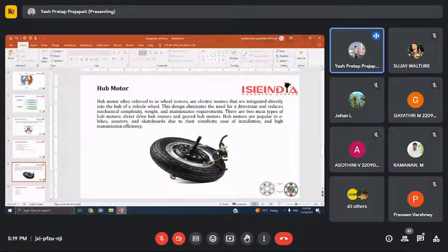Ordinary electric motors use a mechanical device called a commutator and two contacts called carbon brushes to reverse the electric current periodically and ensure the axle keeps turning in the same direction. Hub motors are typically brushless motors, sometimes called brushless direct current motors or BLDC, which replace the commutator and brushes with half a dozen or more separate coils and an electric circuit.